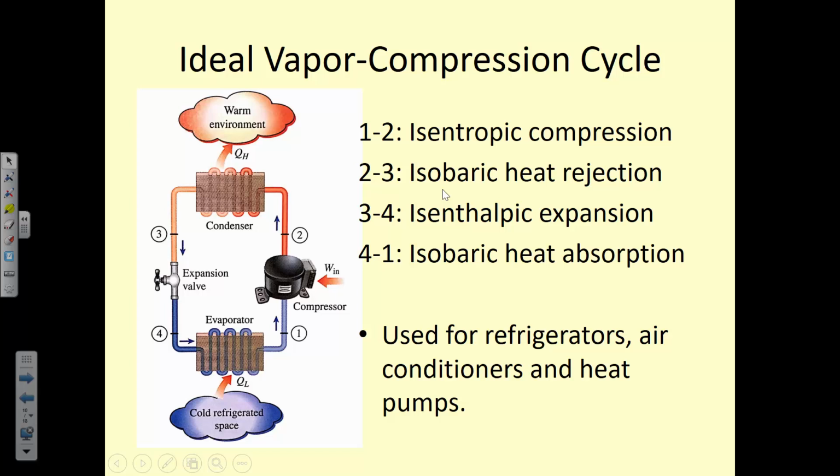So an ideal vapor compression cycle that's not the Carnot cycle, similar to what we had to do with the Rankine cycle, is rather than operating in a perfect square where we're under the dome for the entire portion of it, we're going to have to take a voyage into the superheated region so that we don't have too much liquid in certain parts of our process, or two-phase compression or liquid and vapor if we were to put a turbine in there. So we can do a couple of things.